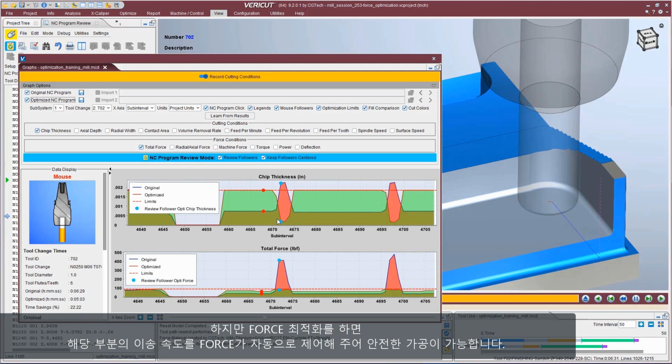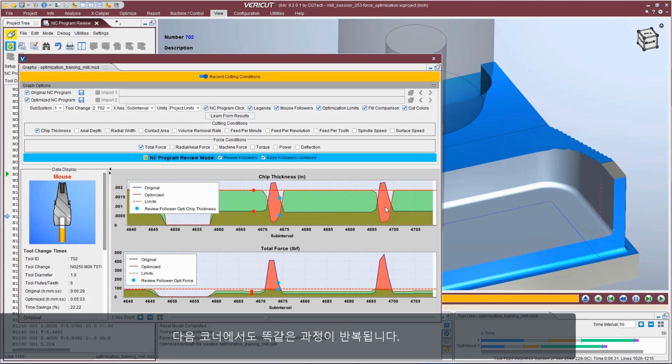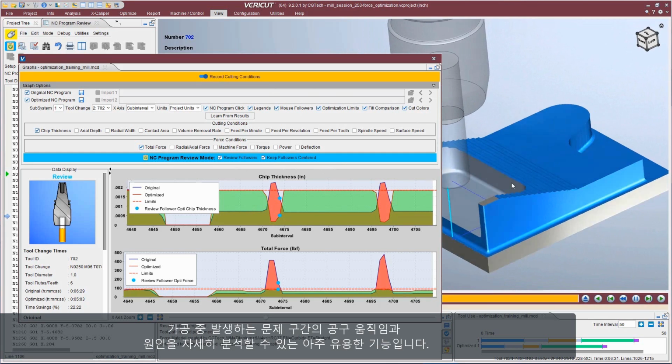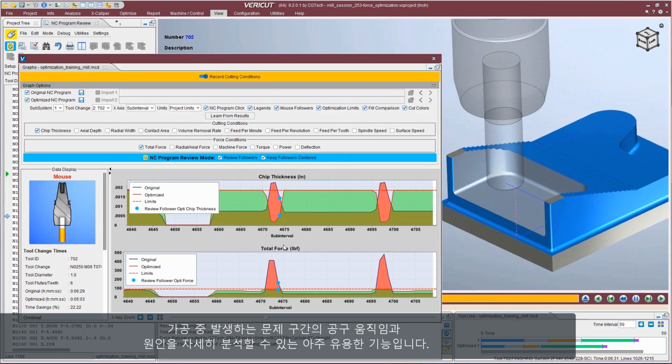That's where it had to reduce the feed rate. So it gives you automatic corner slowdown to make sure your corners come out nice and dimensionally correct. And then it will take off and go into the next corner and do the same thing again. So a very nice way of using VERICUT to be able to go in and analyze the tool motion and investigate problems to learn what's causing them.